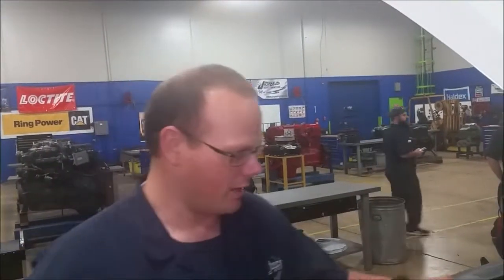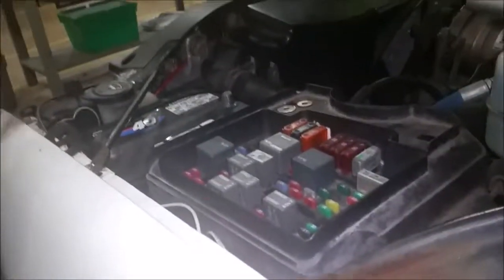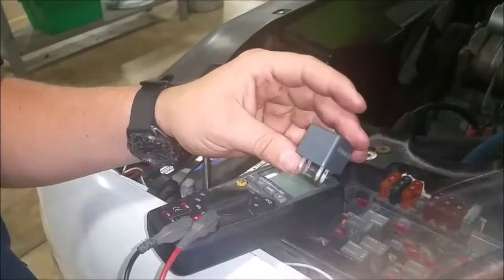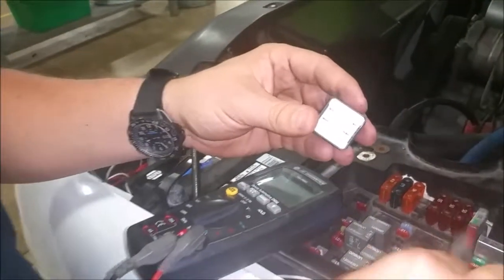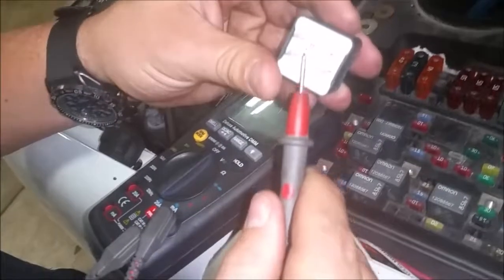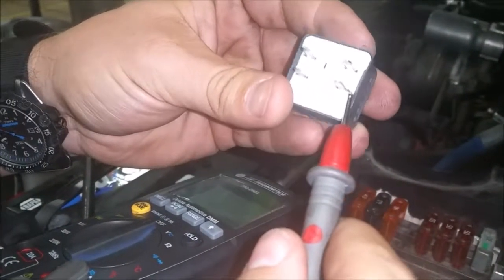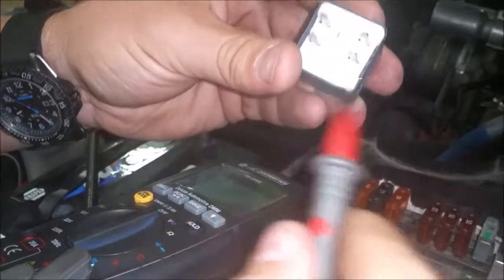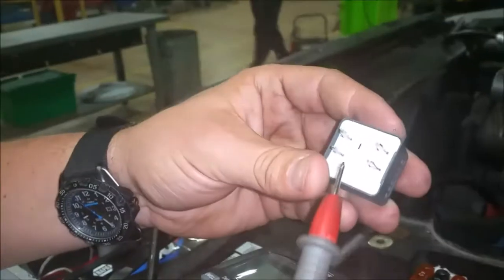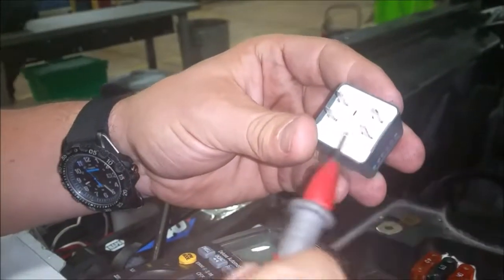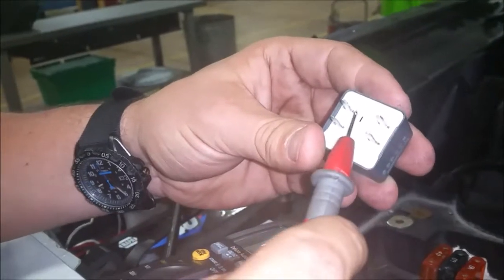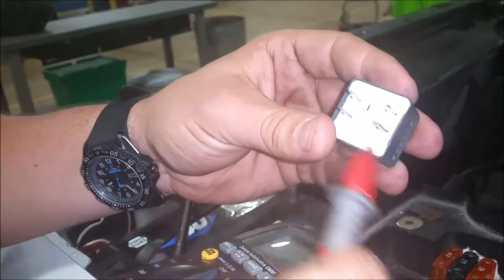So if you look at these relays, this is a relay box inside the engine compartment of this Chevy. We're just going to pull one of these relays. So this electrical relay, if you can read on here, says 30, 85, 86, and 87. It's just showing how the actual relay works. 85 to 86 will be your coil, and from 30 to 87 will be your actual switch.